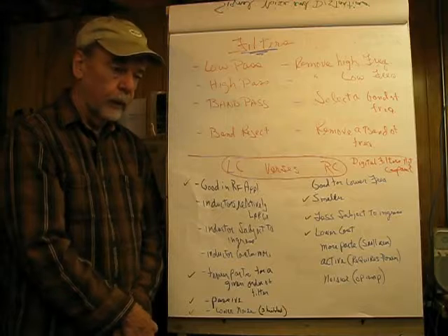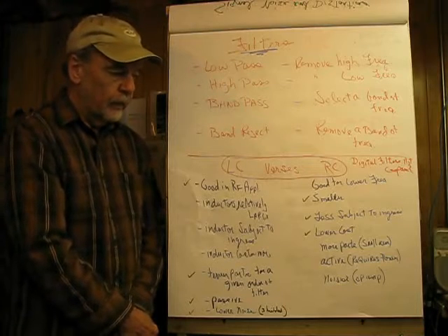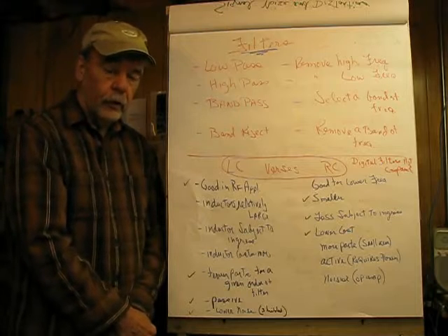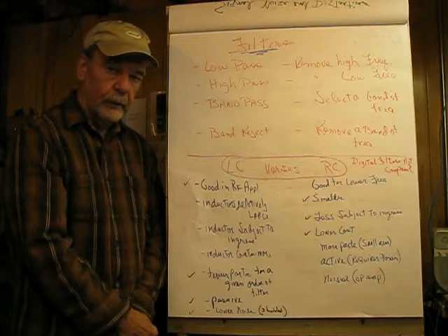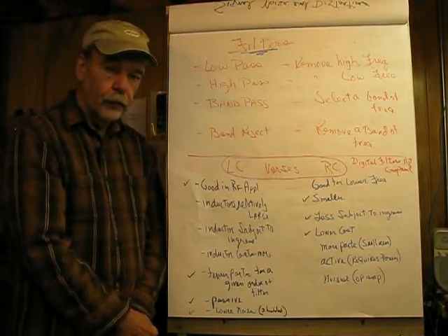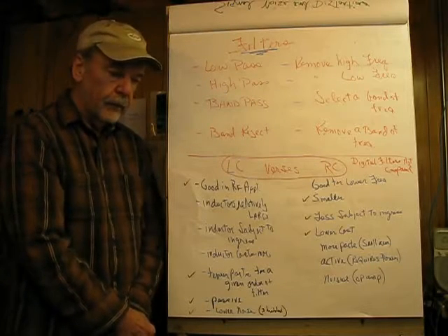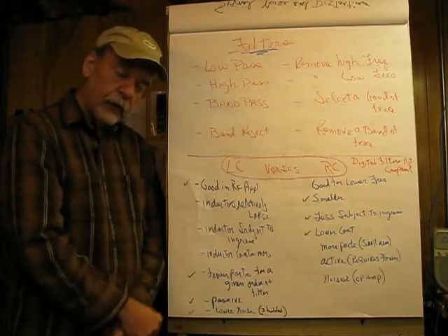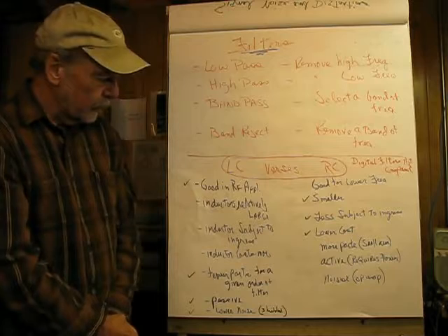And by order I mean that, for example, in a low pass filter with an R and a C, our ultimate roll-off is negative 20 dB per decade. And if we have two R's and two C's connected properly, that would be negative 40 dB per decade. So that would be an example of a second order filter.